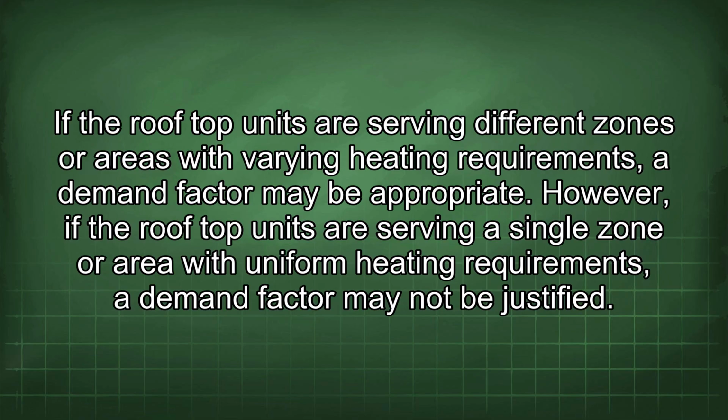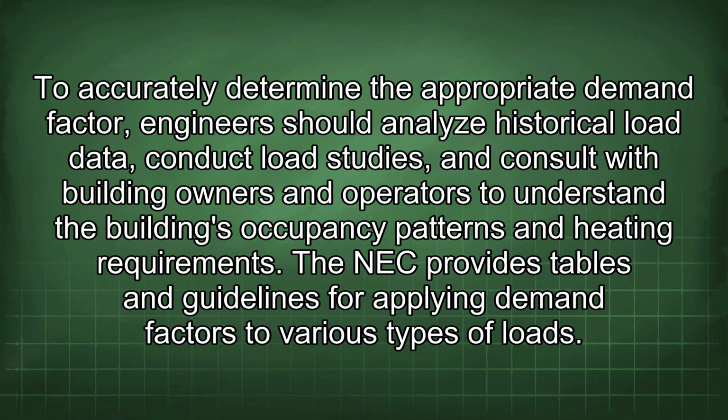If the rooftop units are serving different zones or areas with varying heating requirements, a demand factor may be appropriate. However, if the rooftop units are serving a single zone or area with uniform heating requirements, a demand factor may not be justified. To accurately determine the appropriate demand factor, engineers should analyze historical load data, conduct load studies, and consult with building owners and operators to understand the building's occupancy patterns and heating requirements.